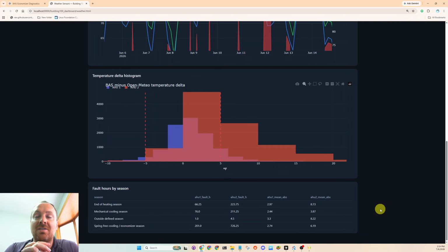And always by design, the outside air temperature sensor is hardwired to the boiler plant, and then it's shared across the building automation system as a networked value. They do that because if the network goes down inside of the building, the local area network or the BACnet MSTP trunk or something, at least the boiler will be able to heat. They've always been doing that for very common traditional practices. Yeah, so very important sensor.